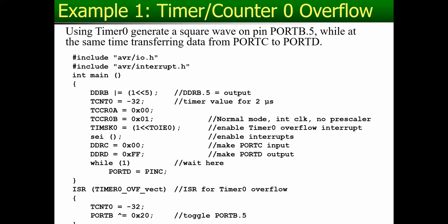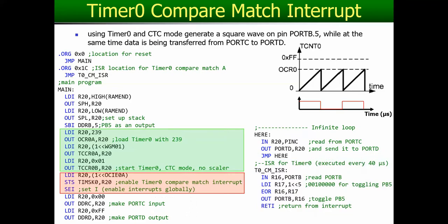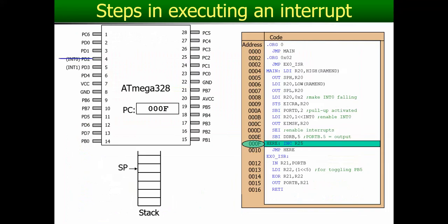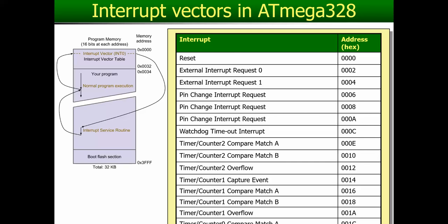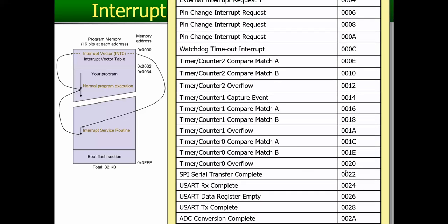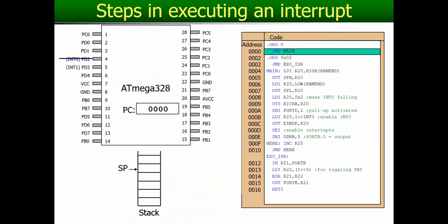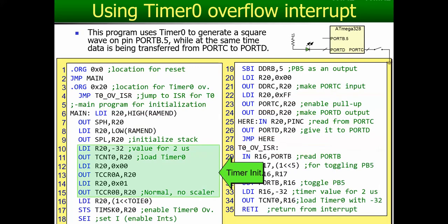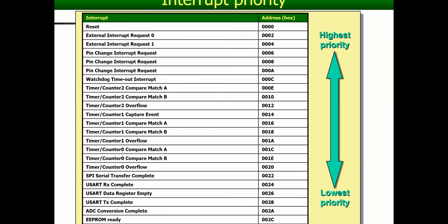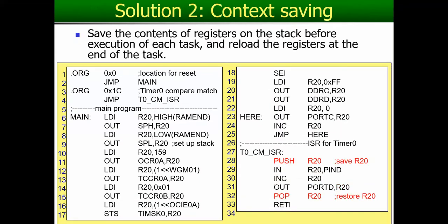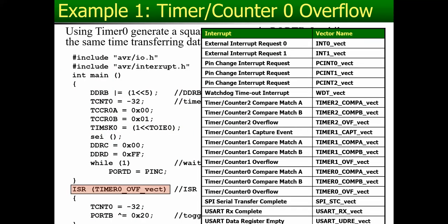For example, if you want to remember the address, the timer 0 overflow vector is at 0x0020. So they have helped us by giving them an English-like name. And I should show you that table of all these English-like names. It's not in some slides, so here you go.